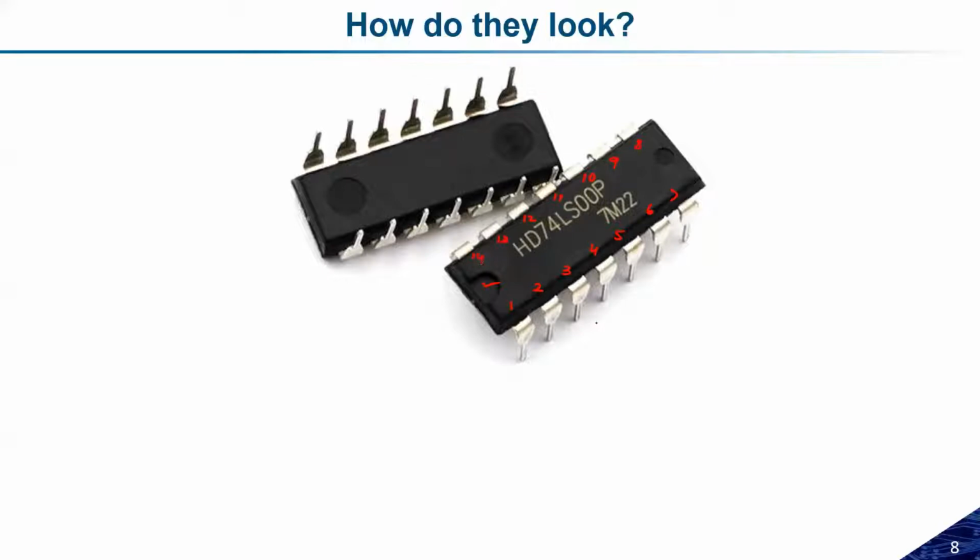This is how we number the pins. If I have to design any logic based on this IC, we should know where to give the input and where to take the output, so this number is really important. Of course, to operate these ICs we must provide supply voltages. At which pin we have to provide VDD and at which pin we have to connect the ground is decided by the pin numbers. So for each IC, the pin number indicates this particular thing.